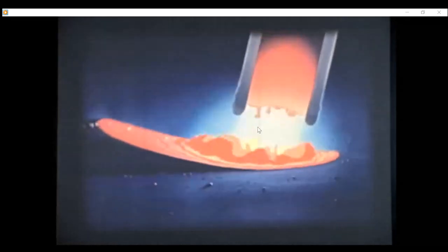So this is arc welding, as you can see here, the electrical discharge. This is a filler. This is a coating. The core is a filler. You see that? The core here will melt and deposit. The filler will be melted and deposited here as a filler material. It is consumable. That's why I said it is a consumable electrode.